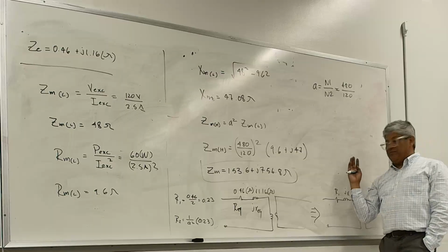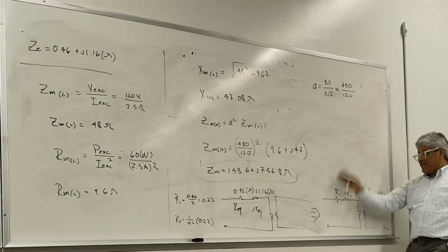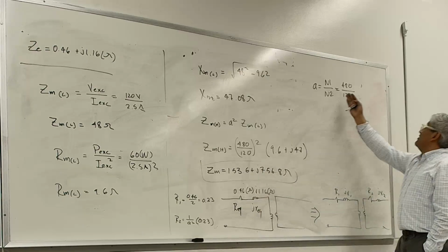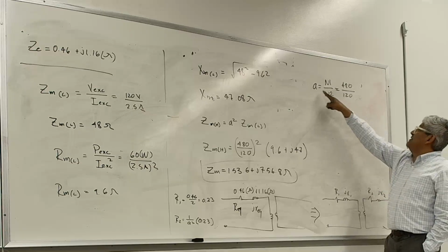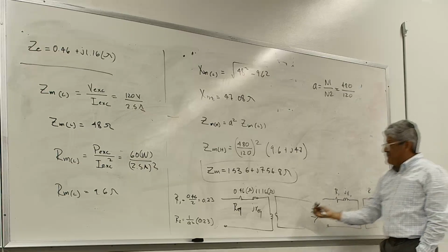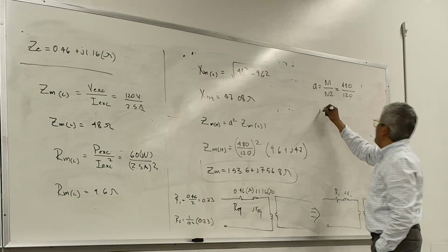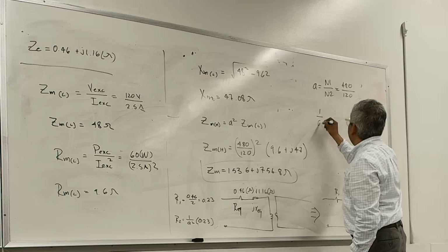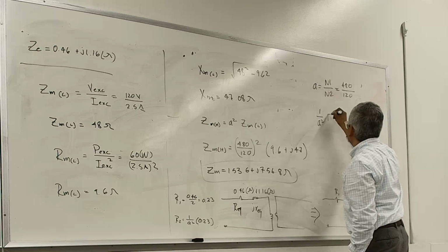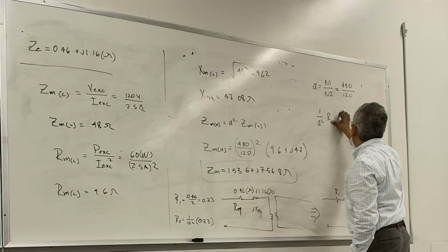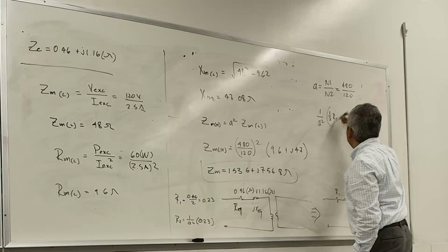When I transfer stuff from this side to that side to get the equivalent, I multiply whatever value I'm given here by the square of this. If I want to transfer from this side to the other side, then I do the opposite, 1 over a squared times, in this case, half of R1.